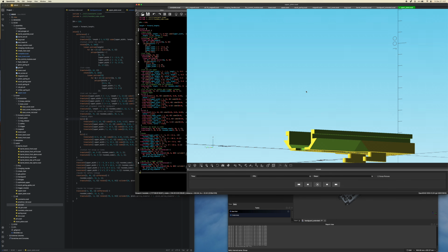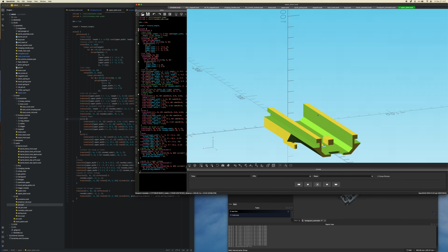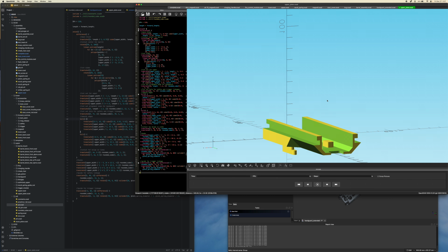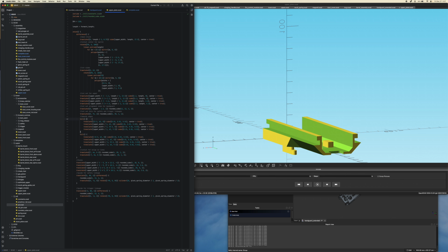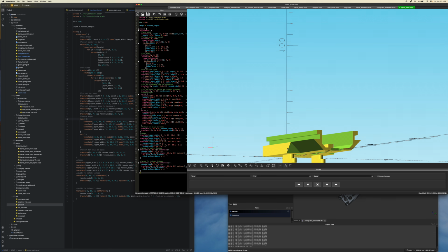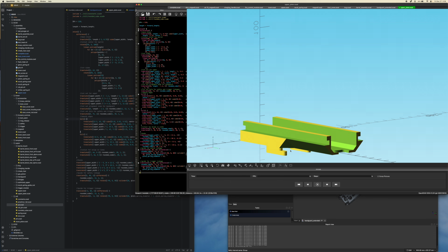The other thing, I mentioned this in one of my other videos, is you basically don't want to have any sort of circular or spherical shape within a hull, because that gives you a line segment error, and it divides that rounded surface into many infinitesimally small line segments, and any CAM software out there, SolidWorks or whatever else, generally has a problem with that.